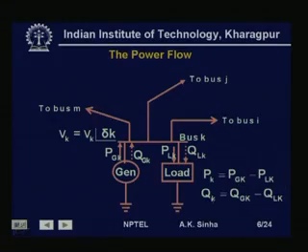For that bus, Pgk is 0, so Pk is equal to minus PLk, and similarly Qk will be equal to minus QLk. So, loads can be considered as negative injection, that is, the loads are drawing power out of the bus, whereas injections we have considered to be positive when into a bus.